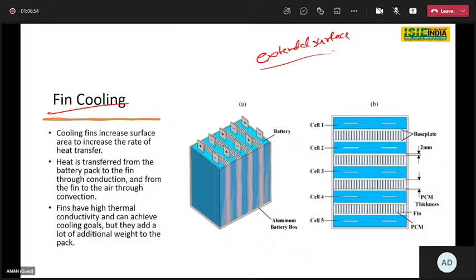In IC engine vehicles, this is also a very popular thing, because in your two-wheeler you might see so many applications of the same. For the two-wheeler segment, I'll just give you one brief idea. Suppose this is your engine. In this engine, you might see some extended surfaces. This extended surface is made of aluminum, because aluminum has a high thermal conductivity, so it is very efficient as far as the thermal flow is concerned.